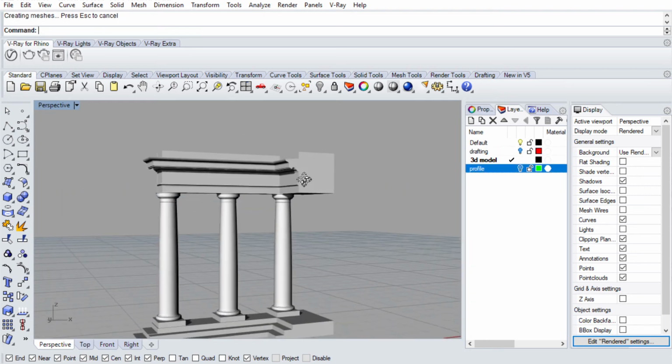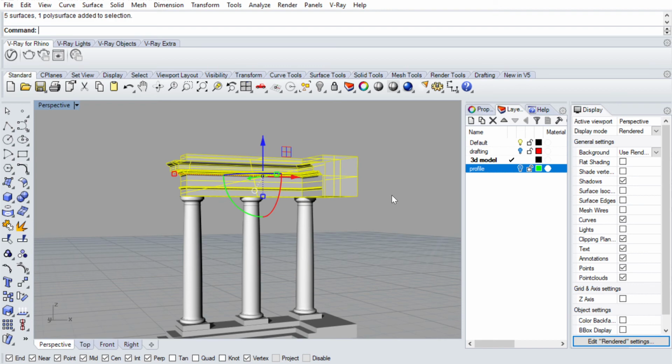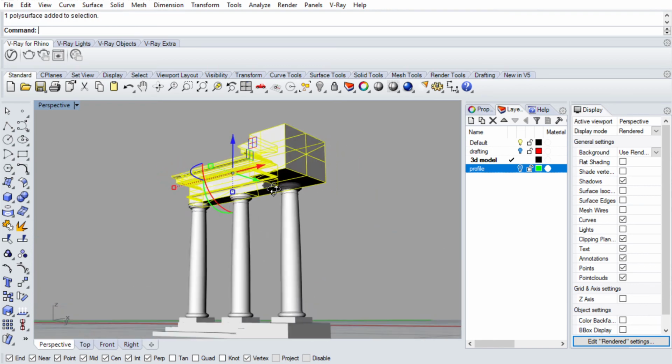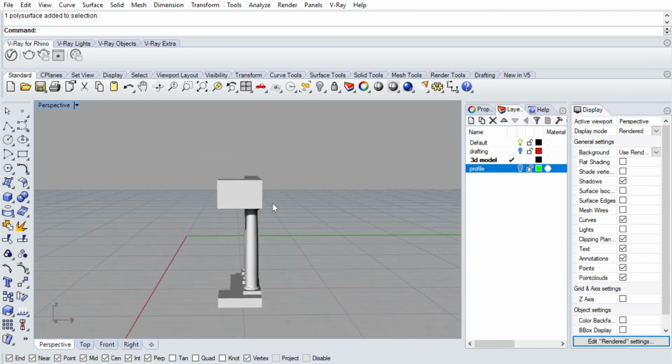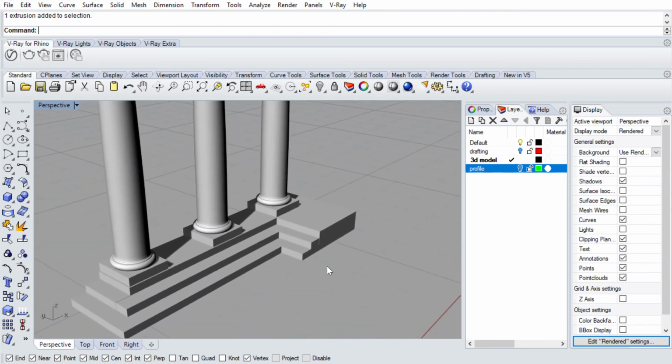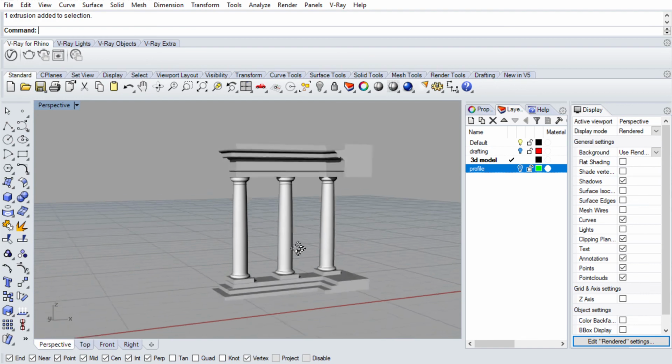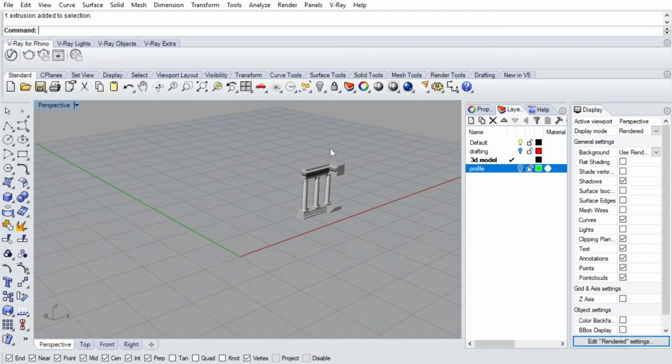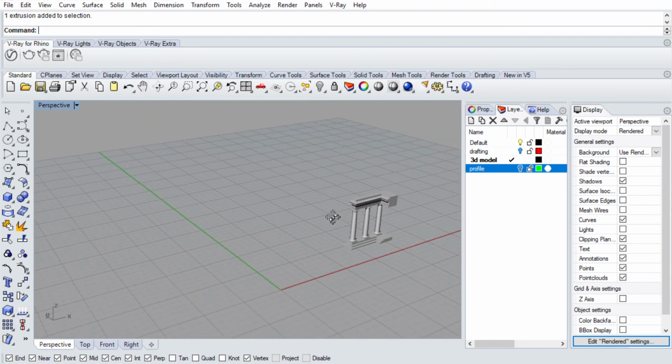curves. Choose the top portion. Type in join. Then that will be a closed geometry as well. So right now, this is a watertight model. We can do the same Boolean operations at the bottom. Now let's go over some of the Boolean operations. For instance,